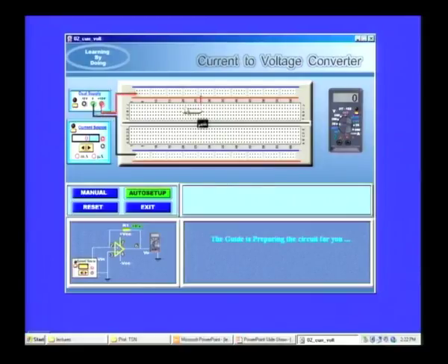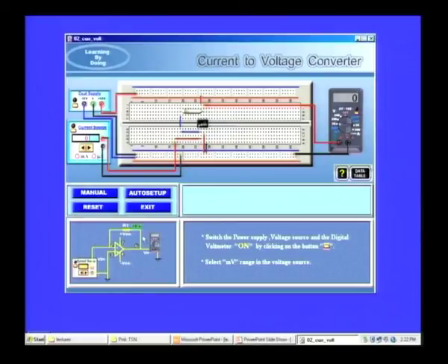So, the IC is put there, the resistor is put there, and the different wiring are done corresponding to the circuit, and the circuit is shown here. It is a very simple circuit, 2 inputs and 1 feedback resistor between the output and the input, that is all. So, that pin number 2 is connected to pin number 6, that is a feedback loop, and the value of the resistor is 10 kilo ohms typically in this case. So, you have the voltmeter here, you have the dual supply, all the things. Now, we will go and switch on the dual power supply, the current source and the voltmeter.